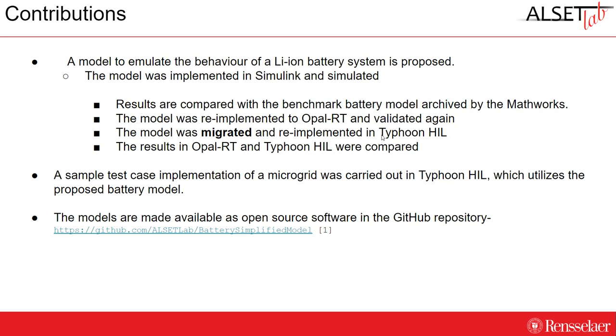So once this comparison validates our model, we migrate our model to a completely different hardware, Typhoon HIL. Once the Typhoon HIL model is implemented, we compare the Typhoon HIL results with our Opal-RT results, and when they match, we conclude that our model is cross-platform compatible and homogeneous.